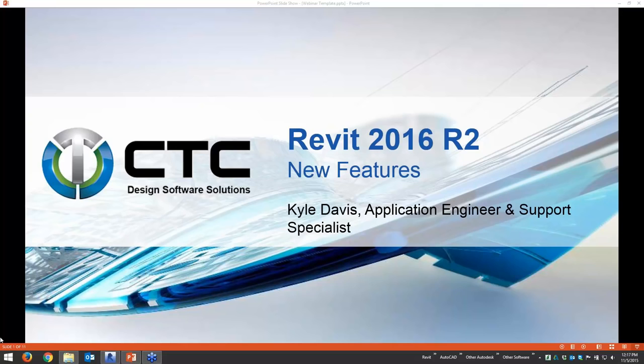It is basically an addition. You do not have to uninstall Revit and then install R2. You simply install 2016 and then you can install R2 over top of it. So again, you do not have to uninstall. It is just an addition. Hopefully in the future we'll see what Autodesk does with the updates afterward. If they release a Service Pack 3, or a Service Pack 3 for R2, that's yet to be determined, but we will keep an eye on that.